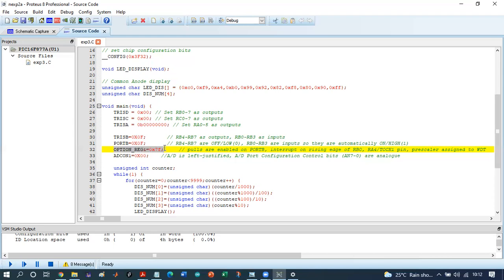When you go deep into embedded systems, sometimes you use embedded systems to program real-time systems. So what are real-time systems? Real-time systems are systems where the time deadline is important. If you want a particular switch to go off at a particular time, and you don't want that time to be delayed, you need to use a real-time system. Interrupts are good at doing something at a very predictable time. So that's why we use interrupts.